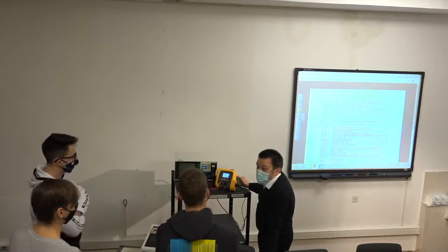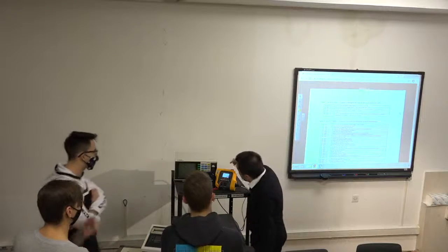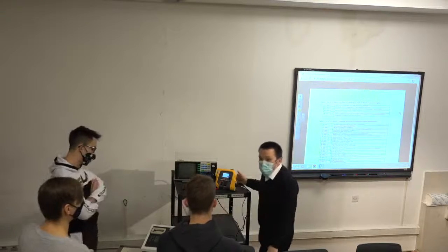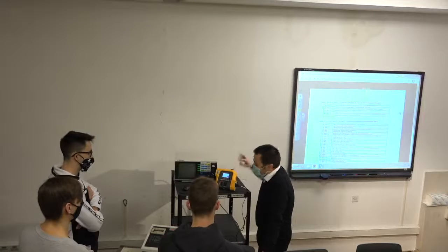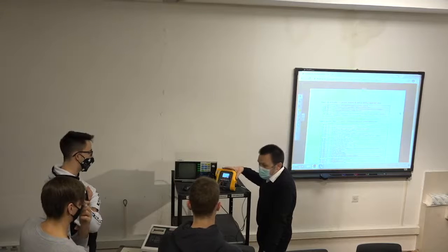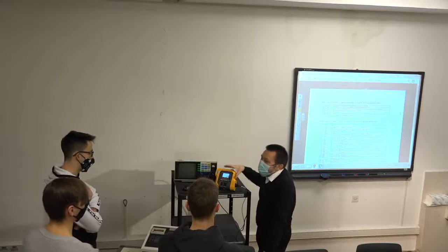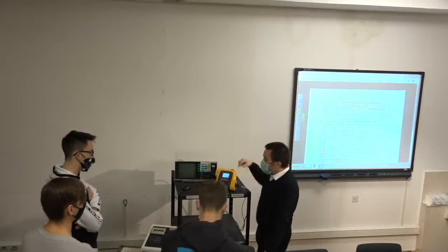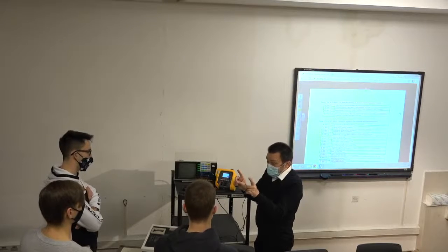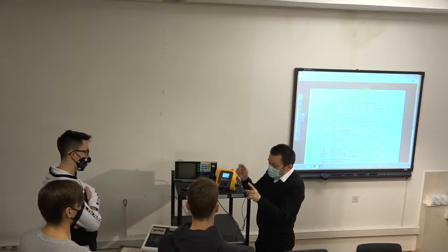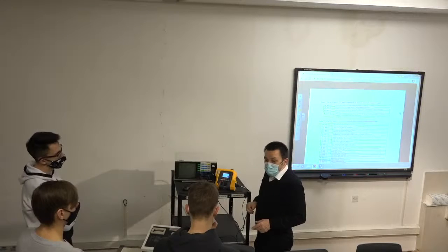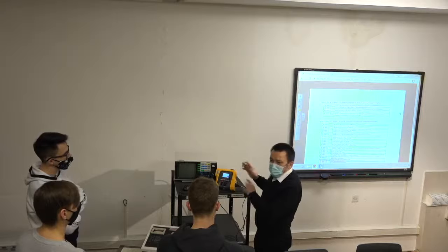Okay, have a look. What's the message? The message is fault detected. What kind of a fault do you have? Just changed the direction, let's say, of the plug. This is the important thing, that the device wants to play, so to say, as simple as possible. So instead of having inside a switch that will change the protective earth and neutral, they ask you to make this change. Once you have done that, now it will be measuring correctly.